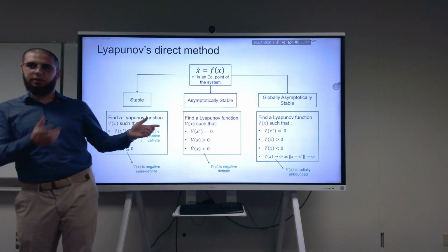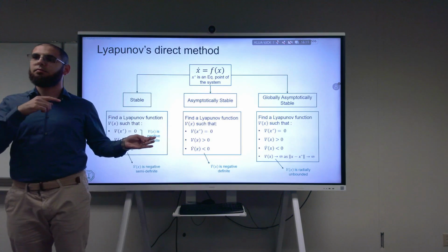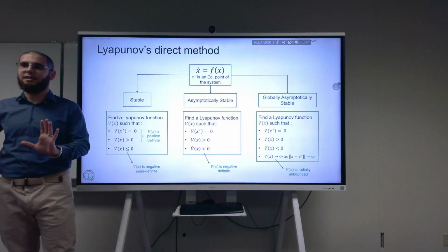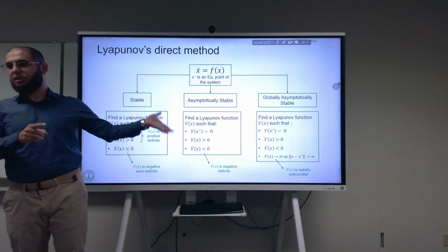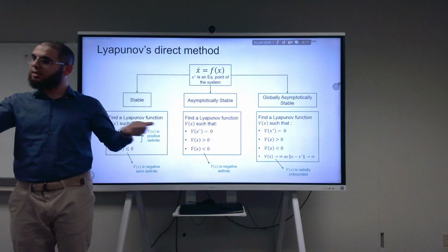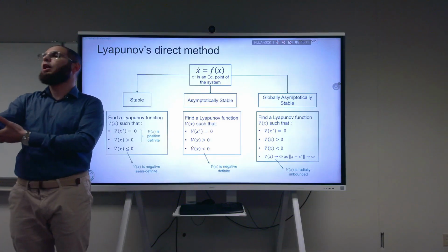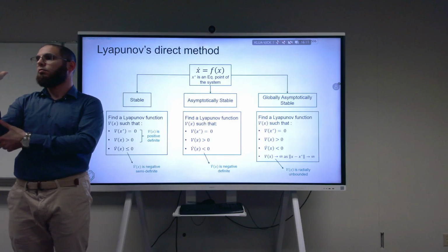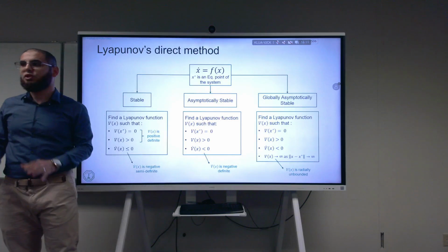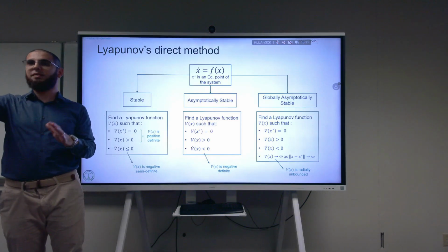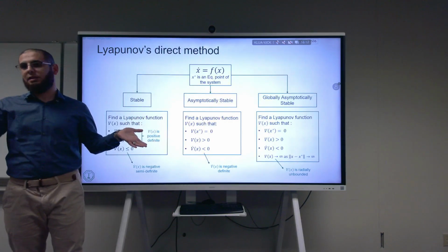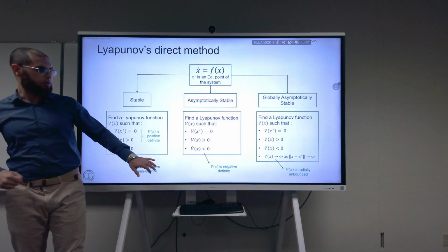Because it says that, you remember? Isn't it the same as stability? No, just the instability itself. So if you want, and that's one of the examples that you can have in the supplementary homework, take the pendulum, linearize it about the top equilibrium point, and check the eigenvalues. What do you get, do you think? Positive 1 and minus 1. One of the eigenvalues will be positive, which means immediately, without solving the system, without integrating it, it's unstable. That's the easy check.